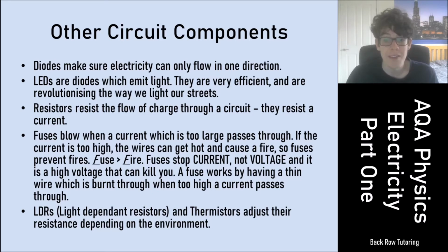A fuse works by having a thin wire which is burnt through when too high a current passes through. So fuses don't stop you getting electric shocks. They stop fires because they prevent too high a current from being taken from the supply.